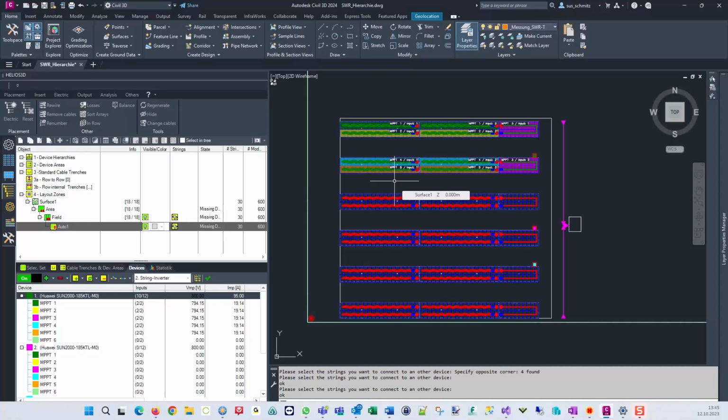After any right-click, the connected strings and modules show the same color as the inverter and MPPT. So we can see any in-between step before we complete the whole inverter. To connect the leftover strings to the next inverter, we right-click again and finally end the selection or assignment mode, and then we select the next inverter and run the connection command again.